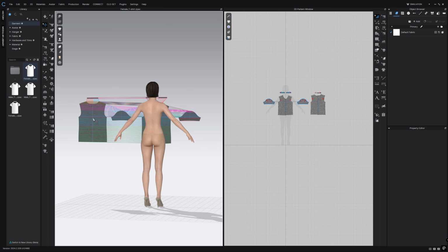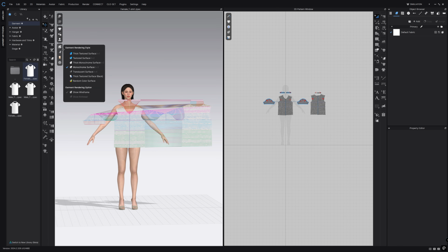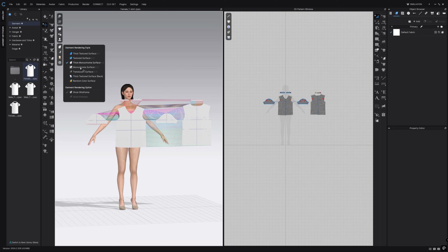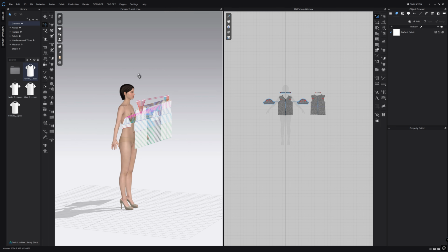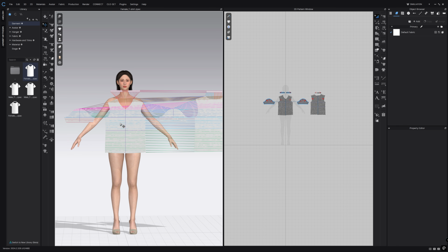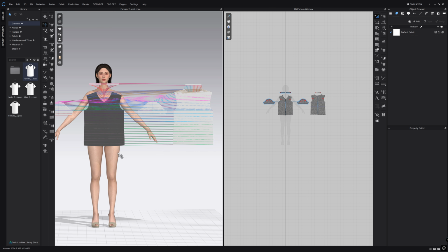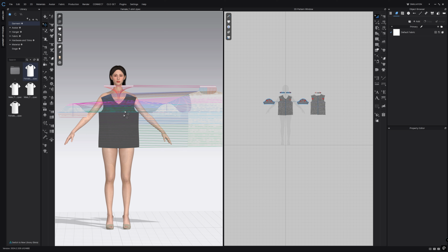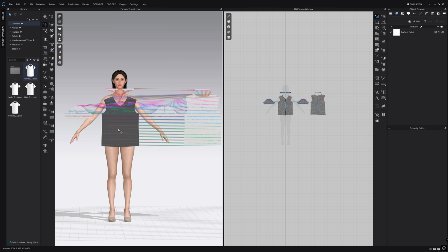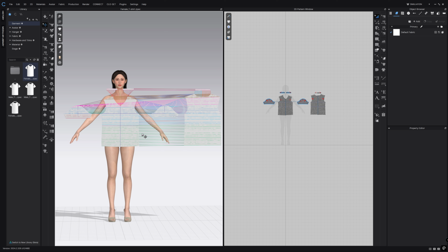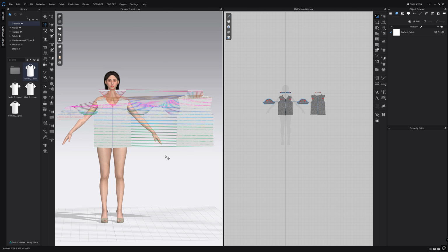And we can see on the back side it is dark and the front side it is white. If you do not see this view, you might be, for example, in thick monochrome surface where the front and the back are the same color. But at this stage, it is important to go to monochrome surface so you can see the back and the front and can see that they're all facing the right direction. Sometimes there could be a scenario where, for example, one of the panels or multiple are flipped. So you have the dark side facing forward, which will cause problems down the line. All of the patterns need to have the white side facing forward. So we right click on each pattern individually that has been flipped, right click and go to flip horizontally. And now all of them again are facing forward in white. This is what we want.